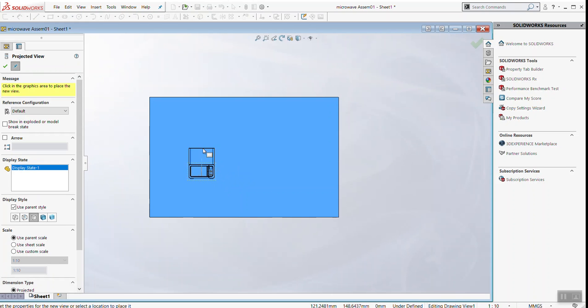Now just click once. Hopefully this is working for everybody. If it's not, I can show you how to fix it. But if you drag up and to the right, you should see a right view appear and a top view appear. Is that working for everybody? So everyone should have a top view. You can click, and then you can go back down here and drag to the right and have a right view. If you wanted, you could keep going. You can even go diagonally and have an isometric. But for project 2, the only requirement is front, top, and side.